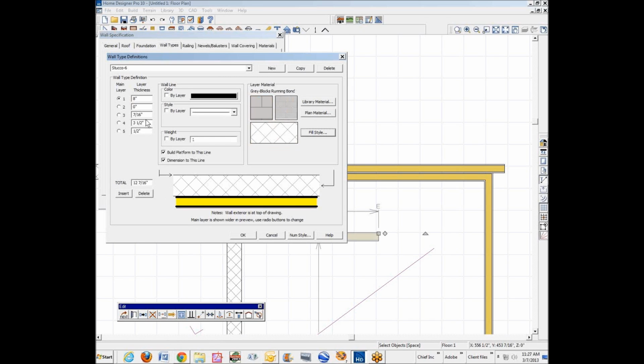And I remember about the gap here. The gap is set to 0 in this wall. We'll set that to 2. So there's a little space, air space between the two. I mean, you need to have enough for this frame wall and your actual plumbing. And the thickness here is going to be determined by the thickness of the plumbing, I suppose. Now we got 3.5. We got sheetrock on the inside, I think. Yep. Okay.